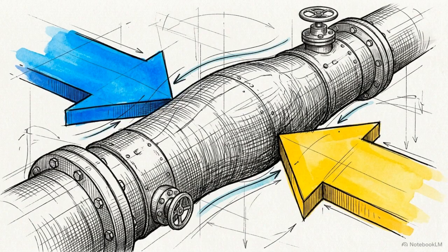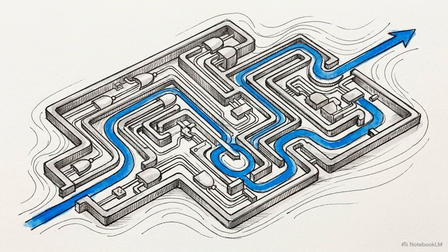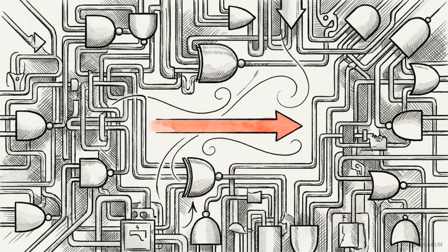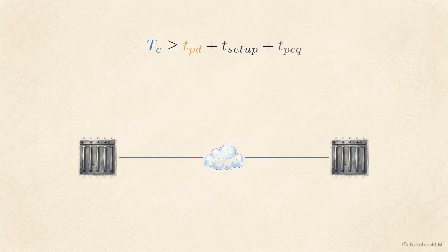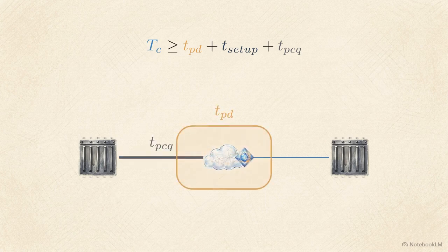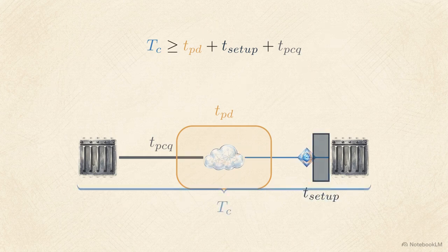Logic delay exerts two opposing forces on the pipeline. Propagation delay represents the maximum time it takes a circuit to resolve a final answer. Contamination delay represents the fastest possible time any signal can ripple through that same logic block. We establish the maximum boundary of the clock cycle using the setup constraint equation. For the circuit to function, the overall period must be greater than the propagation delay, plus the time data leaves the flop, plus the setup time to stabilize the receiver.